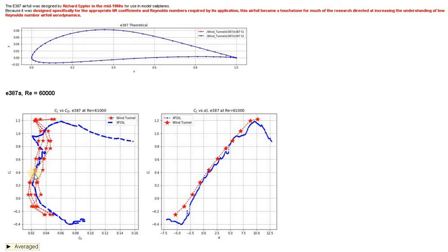So the only question remaining is how to find the lift coefficient needed for the optimal operational point of the plane. And once we know this lift coefficient, we can look at the drag for different types of airfoils and choose the airfoil with the minimum drag, and so on. But first, let's find the lift coefficient.